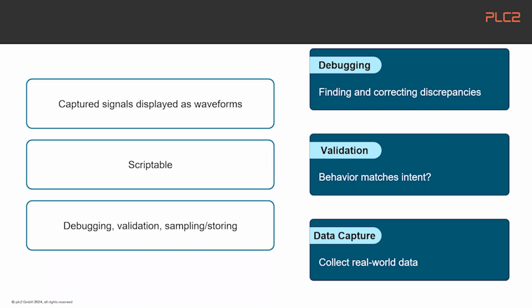These signals collected during debugging may be used during validation as known good data to ensure that whatever changes have been made to the design do not negatively affect the generated results, or as real-world samples to continue testing the design against. And since these samples are captured, they can be played back or even modified to generate useful corner cases when offered as a stimulus back to the design. So therefore, it's a wide range in which way you need your validation concept, but actually the ILA core here is quite essential.